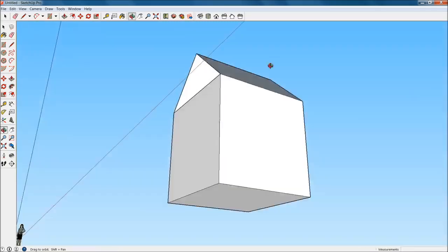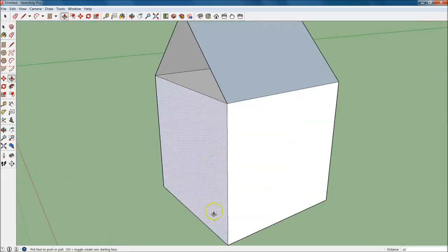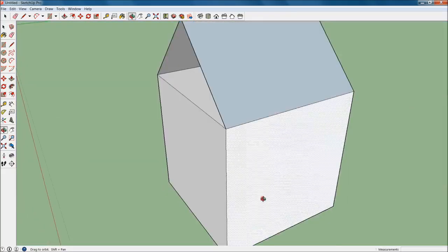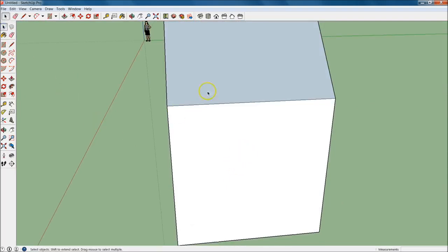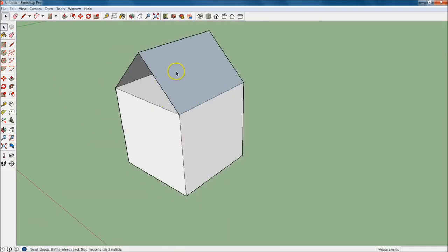So in SketchUp, there's really no material applied right now, but the default is to have this white with this light blue on the back side. So if I were to click this, well, let's skip that part actually. What we're going to do is undo that real quick with Control Z, and do the push-pull tool right there. And as we're pulling back like this, you'll see that it goes blue, right? I want you to just hit Control. Did you see that? I just hit Control. Now on the Mac it'll be Command. If not, somebody comment and say it's not. But you're just going to pull it back and then drop it on that point right there.